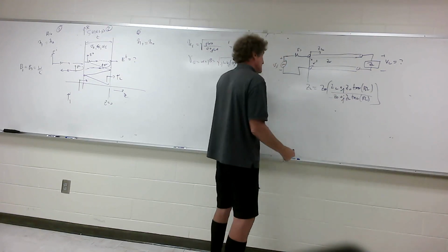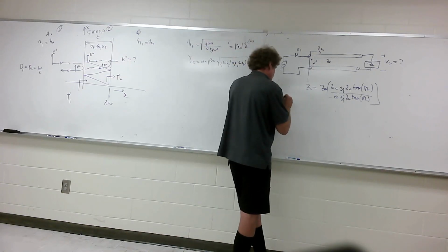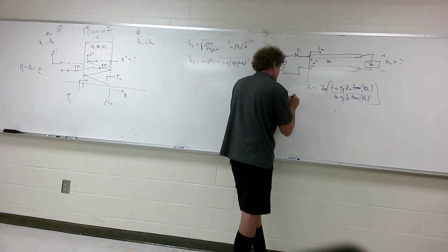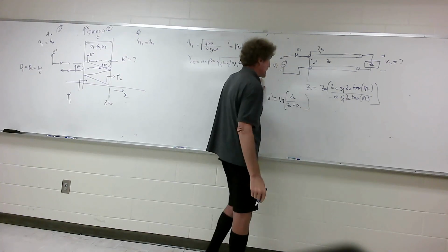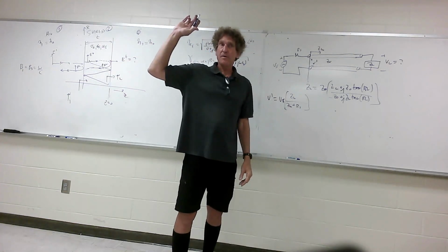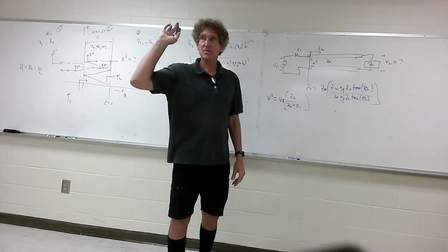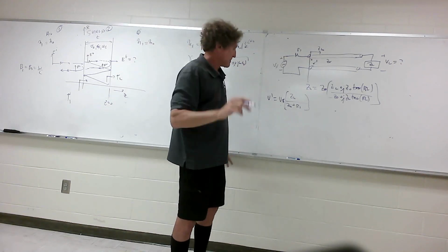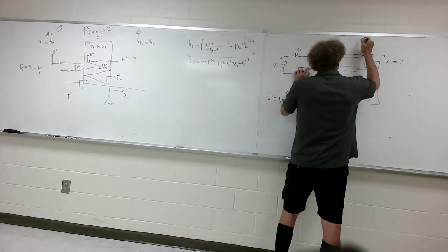That would be Zin. Then what you do is say that V prime here was equal to Vs, whatever that scalar value is, times Zin over Zin plus Rs, and you would get V prime right there. Do you all remember that? How many do? If you can give me a page number, you got the book right there, of where this is with transmission lines, please do, and I'll give it to everybody so you can refresh your memory if you don't remember stuff.